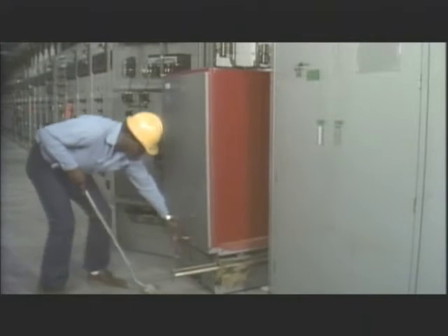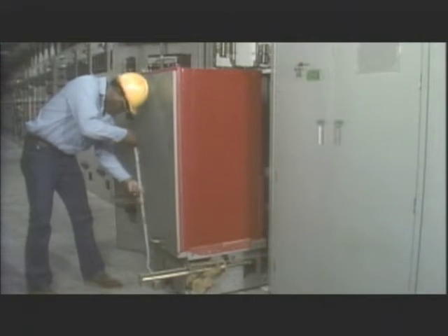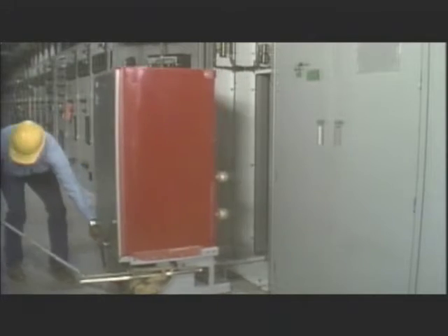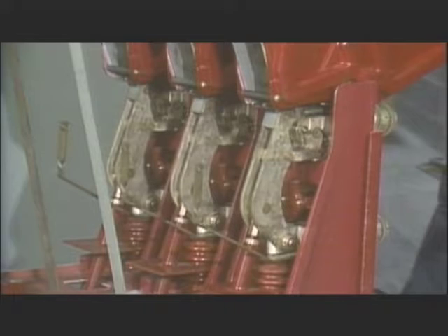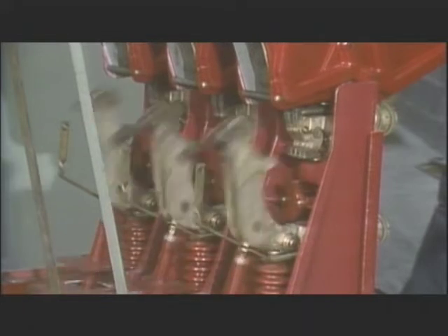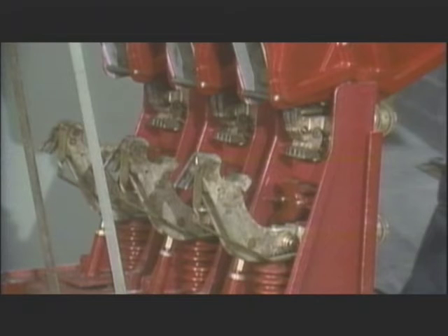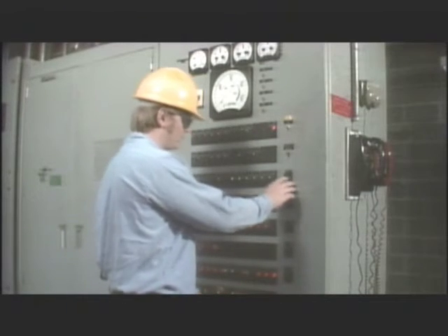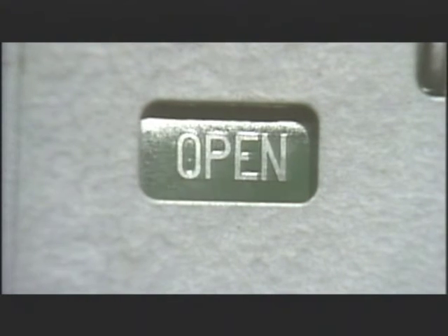This is an air circuit breaker. It's a piece of control equipment for manual or remote operation of substation circuits. Like other circuit breakers, it's basically a switch. It's called an air circuit breaker because the switch contacts inside are open to the air instead of being submerged in oil. A control device outside the enclosure can be used to manually operate the breaker. This indicator shows whether the breaker is in the open or closed position.